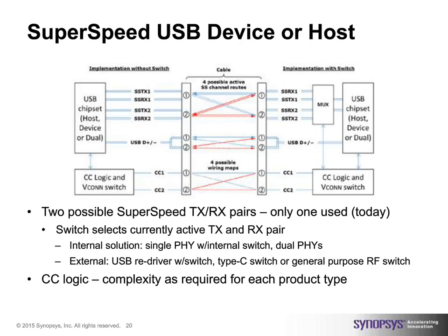When you create two possible routes, as you do with D plus, D minus, as shown here, one signal goes to the receiver and is terminated, the other goes into nothing and is reflected back to the transmitter. It's just like when you have an echo on your phone connection.